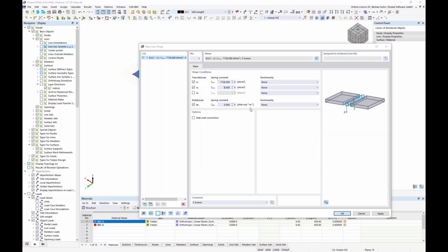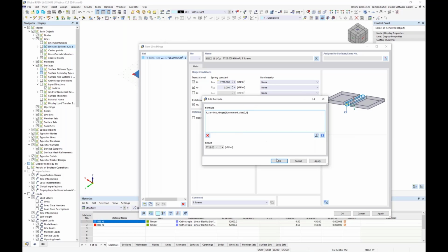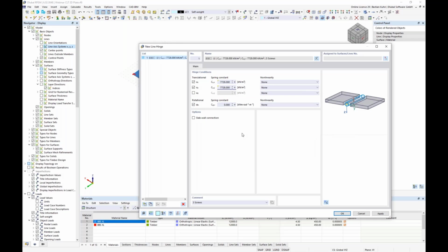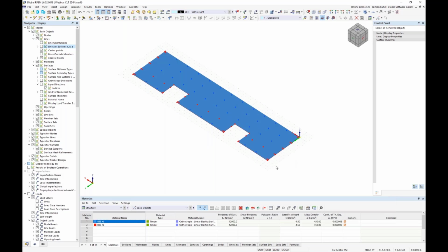Okay, so then second, we do it also for the Y direction, because according to the spring laws, you need to have it in the plate area for X and Y direction. Rotational spring constant, with newer researches, it is also possible to define a value in here, but right now I'm leaving 0. Of course, you could have something similar, like I did it for X and Y direction, also for the rotation. And Z direction is not necessary to define any kind of slip.